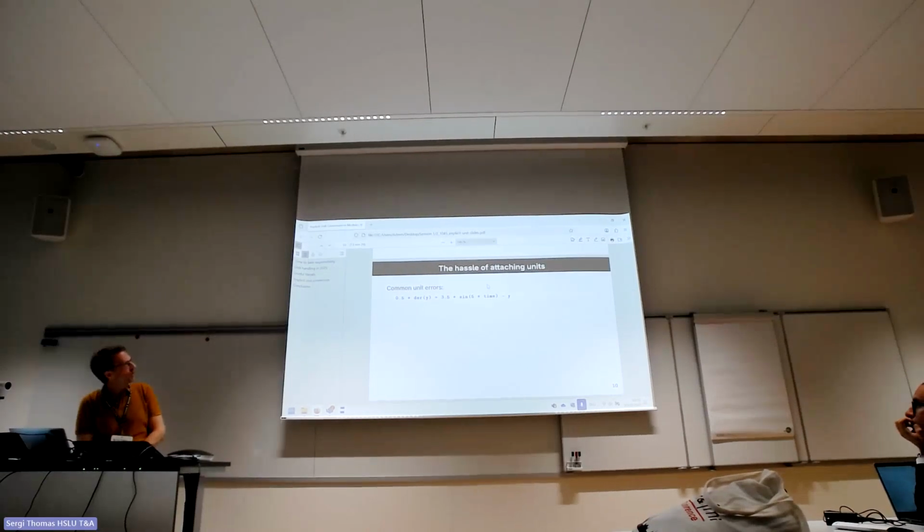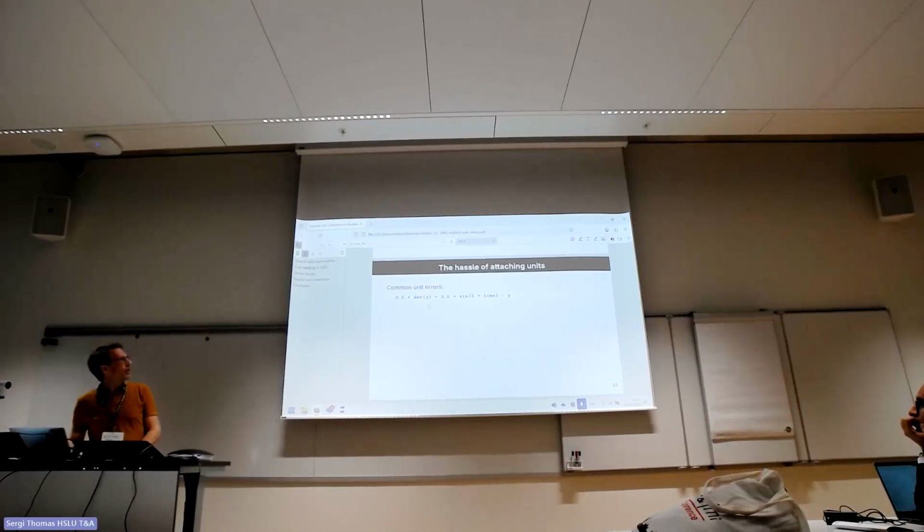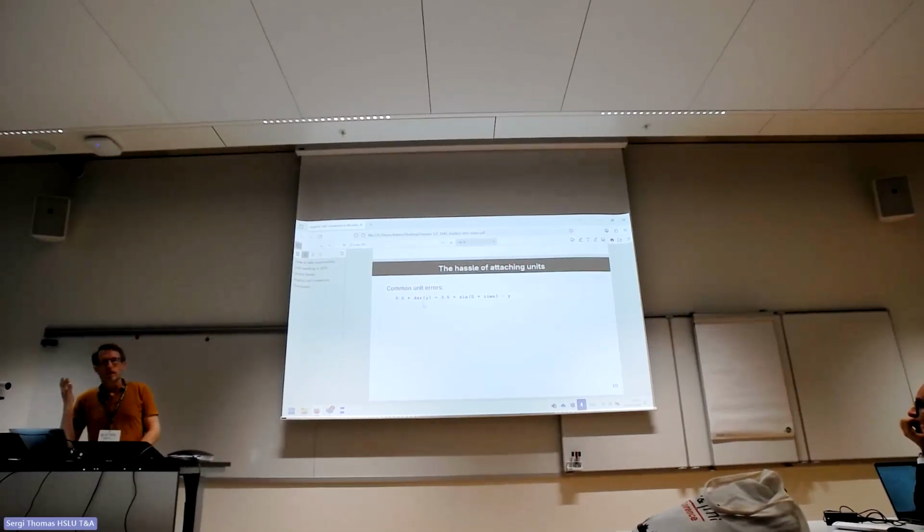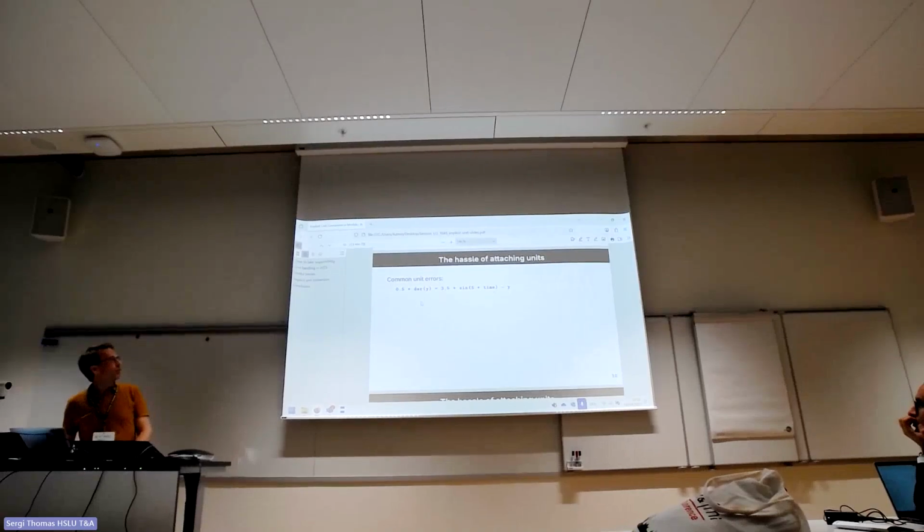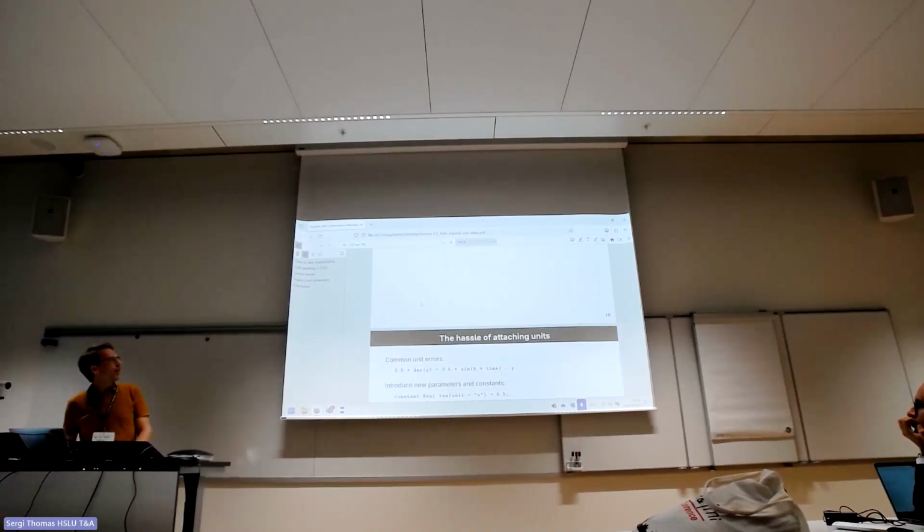But of course, you're taking the sine of a time, and there's a hidden per second here that is also messing up the units of your equation. And the way you're supposed to solve that in Modelica today is that for each of these numbers, you introduce a new variable in your model.